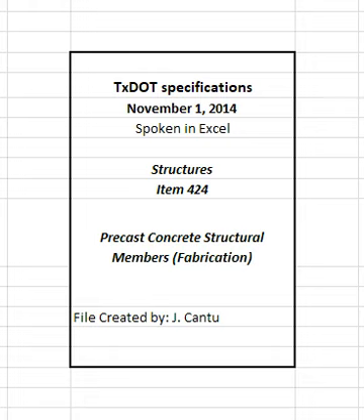4.2.7.4.1 Steam curing. Steam cure in accordance with the requirements of accelerated curing. Position steam outlets so live steam is not applied directly on the concrete, forms, or test cylinders. 4.2.7.4.2 Alternate methods. Other methods of accelerated curing, such as the use of radiant heaters or portable heaters, may be permitted if they meet the requirements of accelerated curing. The use of any alternate method requires written approval.